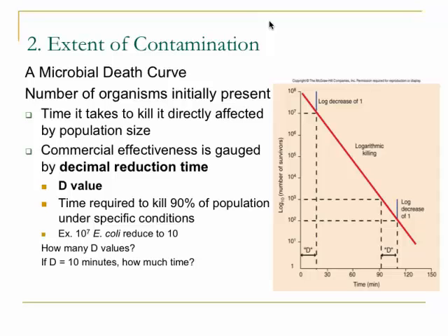It's an actual measure of how much time it will take, but it would be different depending on the temperature where you do disinfection. Chemicals are a little bit more effective at higher temperatures, and they tend to be most effective at neutral or near neutral pH.